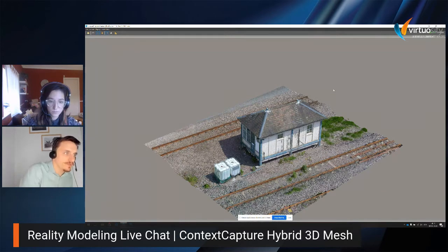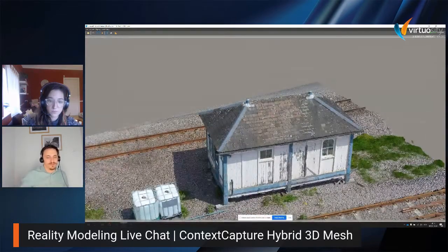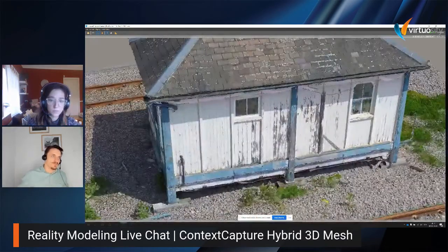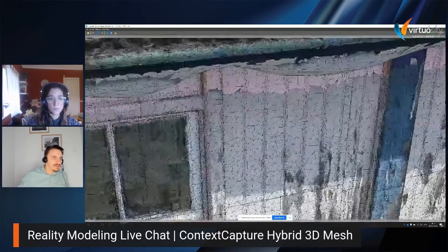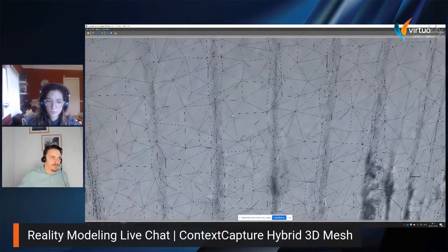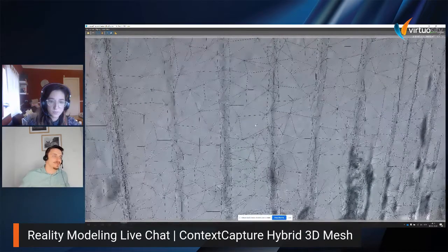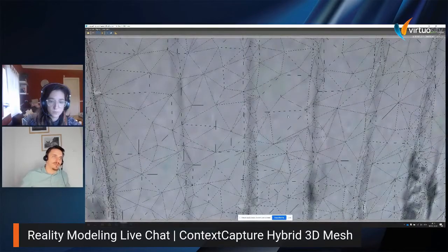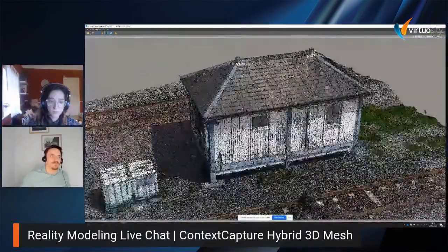But with a drone, we can fly in a much shorter time to gather proper pictures, with the proper quality of the camera of course, and then we finish with a product with much more natural colors, because the mesh will get information. What information is, I'm going to show it here. If we are using only a point cloud, then we have a point here, a point here, and here we don't know what is going to be happening, because we have to interpolate a color. With the pictures, we have information because we just cut a picture and we got information stored here. So that is also the big difference.